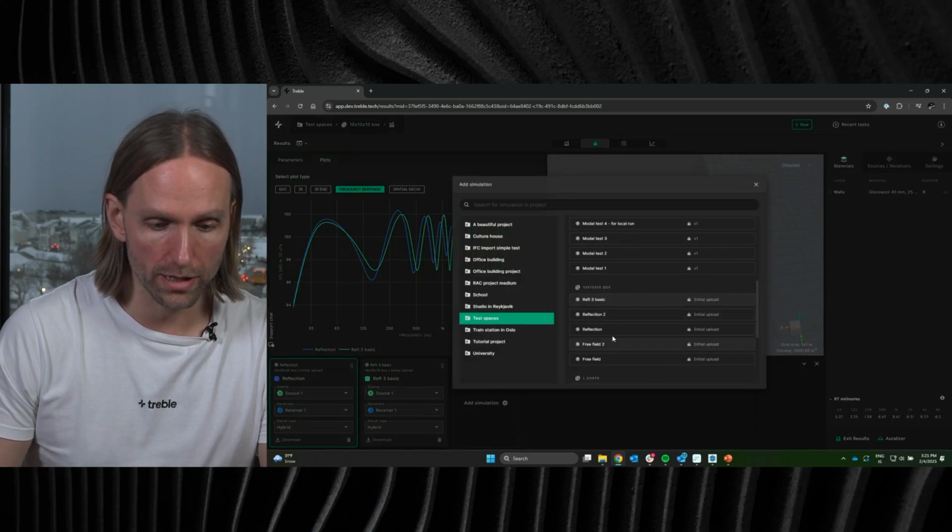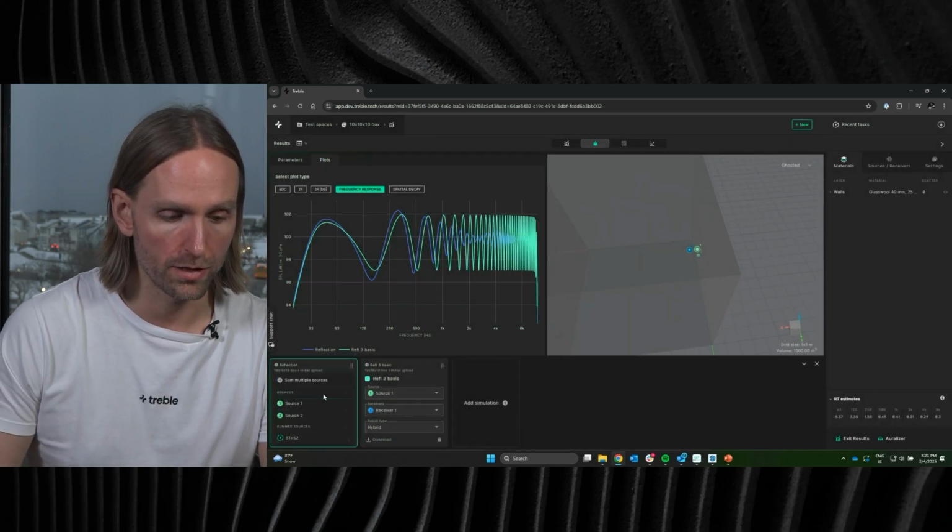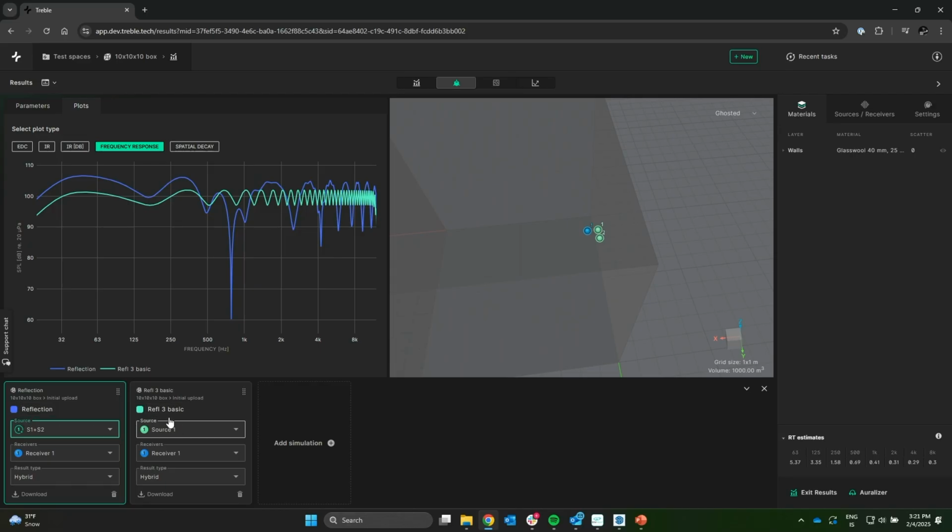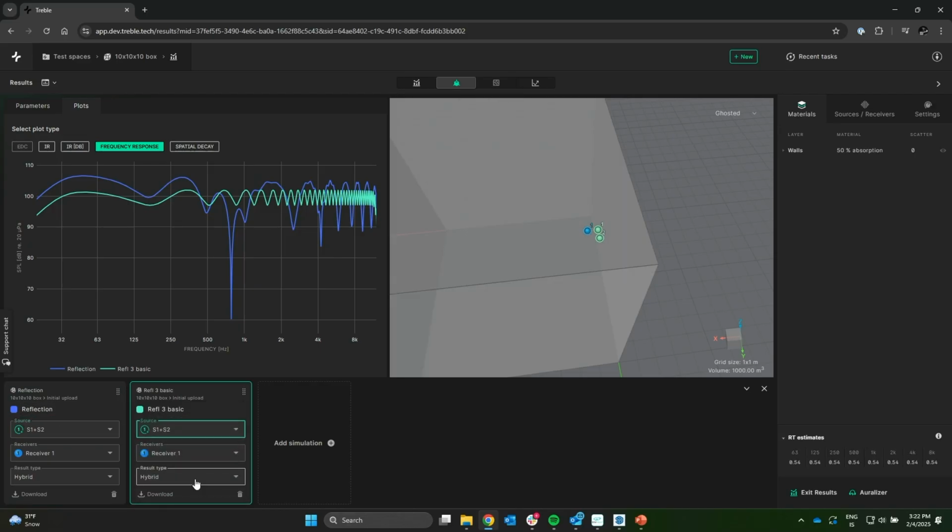And this certainly continues if we look at summed sources. So here for these two cases of the different materials, if I have two sources hitting this wall and being reflected back, the frequency response is actually quite different due to both the amplitude response and the phase response at the boundary. So this was maybe quite detailed acoustics nerdism, but it's just to highlight that materials are modeled in a more precise way than what has typically been done in the past in Treble, preserving not just absorption but also phase properties, also in the solvers themselves.